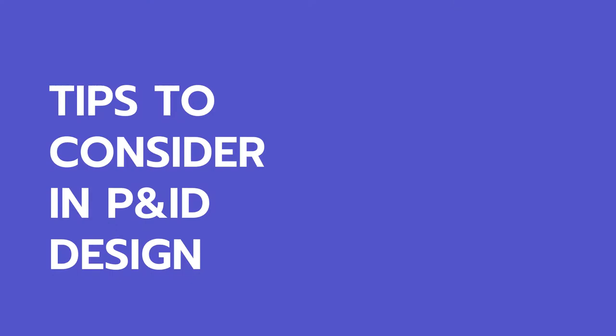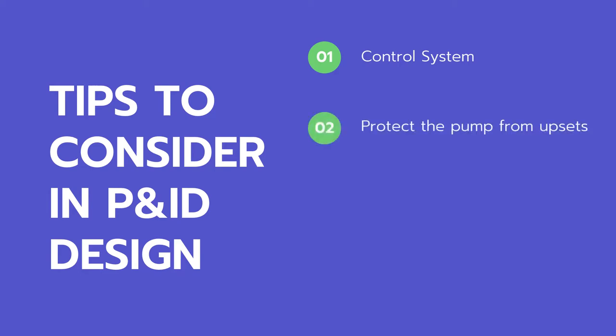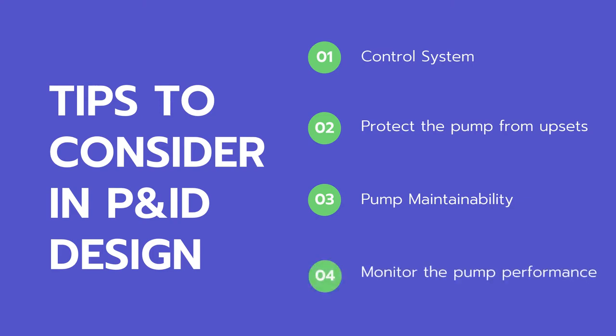So what are the tips we need to consider for the P and ID drawing of a pump? We need to consider a proper control system to control the pump operation. We should protect the pump from upset conditions that may cause pump damage. In addition, the pump should be maintainable, so we need to isolate it in case of shutdown. The P and ID should provide the means for the operator to easily monitor the pump performance. We shall see each of these tips in detail.